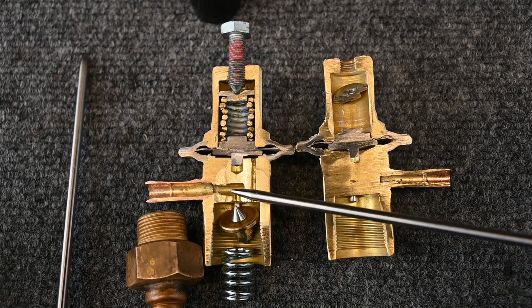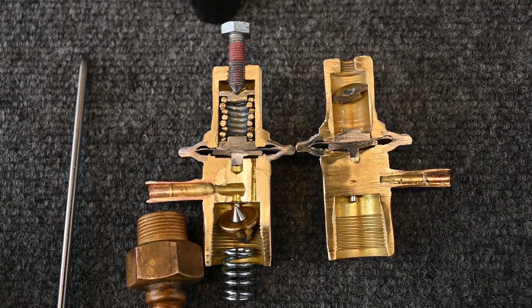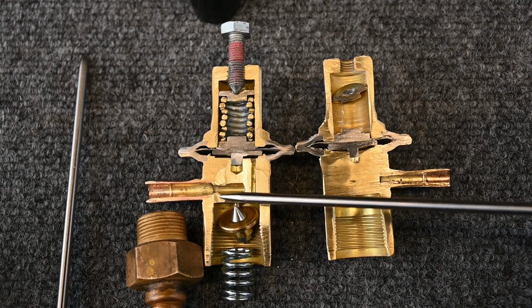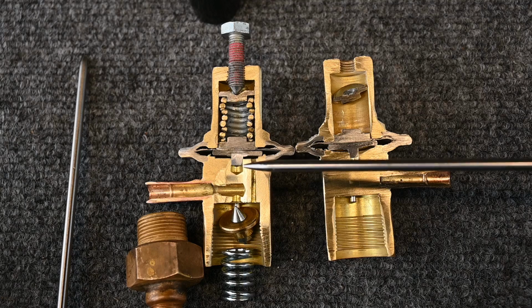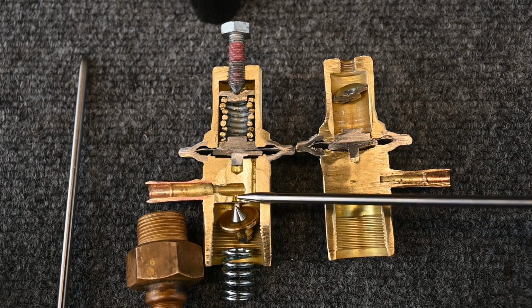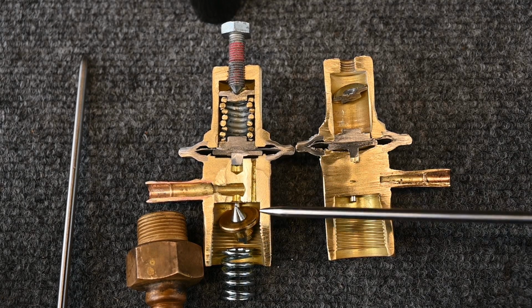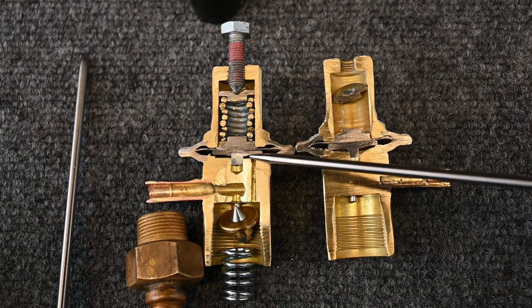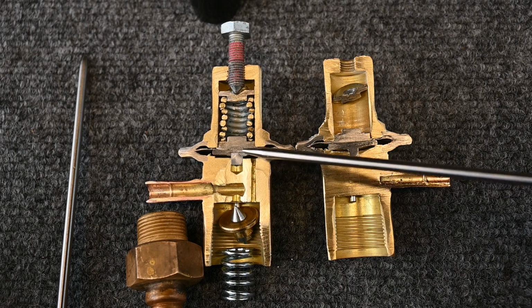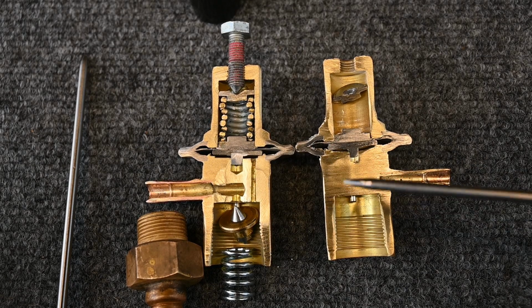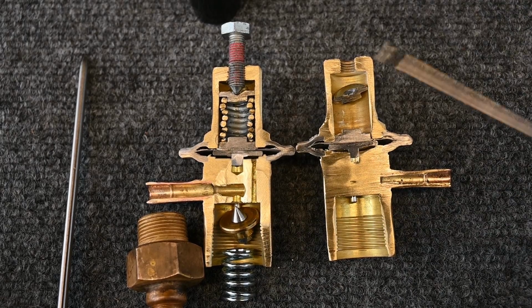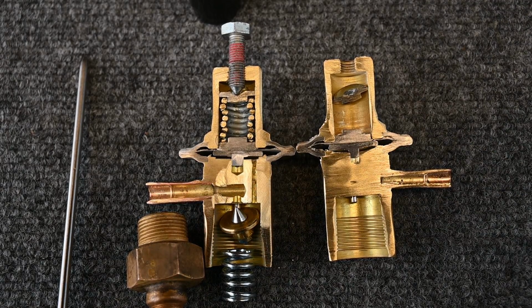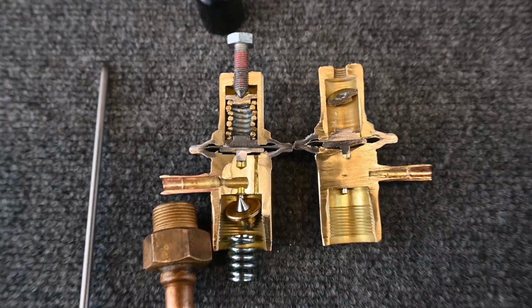As you can see, getting dirt or debris in here is going to be an issue. So if we didn't braze with nitrogen, any of those flakes in here, if we left debris in the piping, if we didn't cut the copper correctly, any of those debris can stop up our metering device here, it can stop up our tube here, it can get up in all of our moving parts here, it can get around where the pins are here. So we want to keep all that debris out of these moving parts. But I find these absolutely fascinating how they work. It's quite a simple design overall.